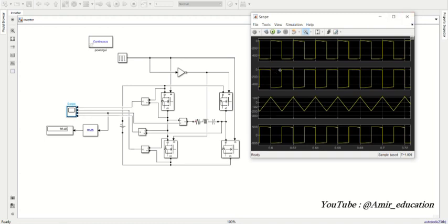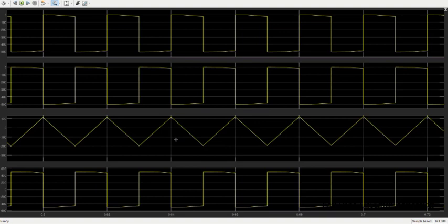So as we could expect, the shape of each pair is opposite to the other one, but the most important thing we want to discuss is in this area, which, as you can see, from this part until this part, each of diode 1 and diode 2 is activated until this place. And this is because of our inductance effect.